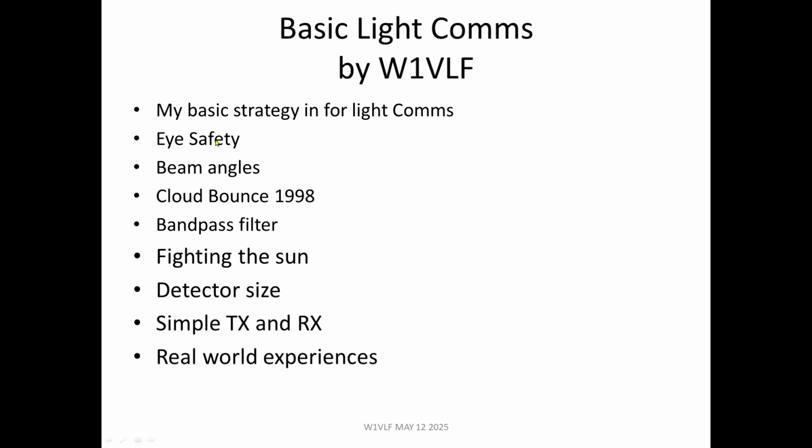The next thing is eye safety. Like the 10 gigahertz guys and microwave guys or anyone, you wouldn't stick your eyeball down a waveguide with 10 watts of RF in it. Just like you wouldn't sit and stare at the large array I showed you before. It's a 6-degree beam width, so the light spreads pretty quickly, but we're going to talk about that in the next section. Just use common sense, right? Don't stand in front of the thing for half an hour looking into it, trying to say, hey, can I see it? No. It's not good. So at your own risk.